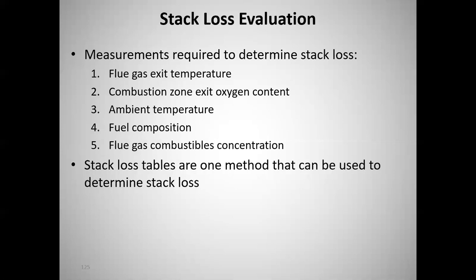Fuel oil should be really a pretty consistent fuel. And flue gas combustibles concentration, you're measuring your CO, that's a combustible, or unburned hydrocarbons, or unburned fuel molecules that are in the flue gas.